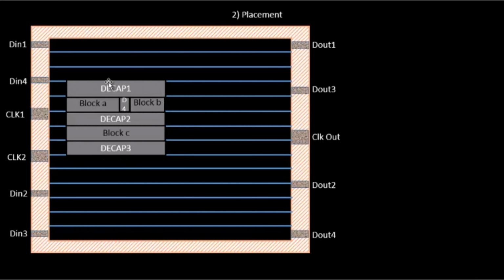So these steps are done in the floor plan stage. The placement stage, the stage where we do the placement, will make sure that these particular locations are not affected. They are not moved. They are kept as they are. And the second thing that it will take care of is that no cells will be placed in this area. Okay, so these two things we have to take care of. Let's move on with the placement step.